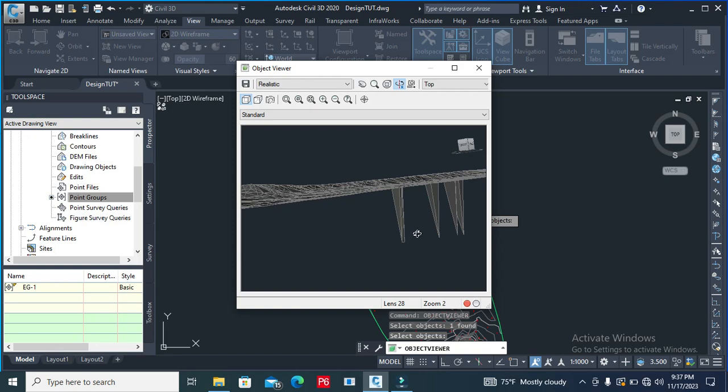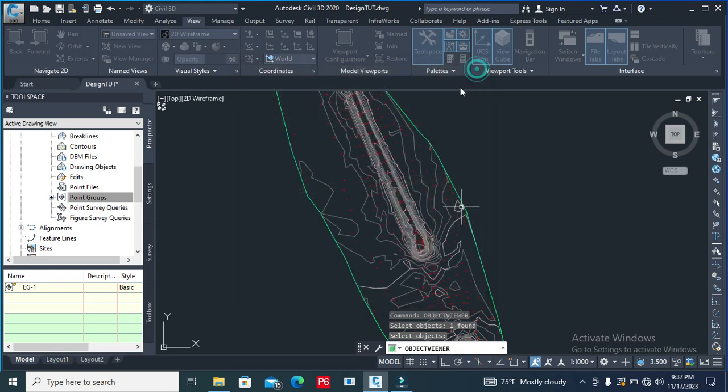So this is where you can go into the settings, change the surface properties, and change the triangulation length, as we are going to see, in order to eliminate such obscure data which falls outside what you would want to see.